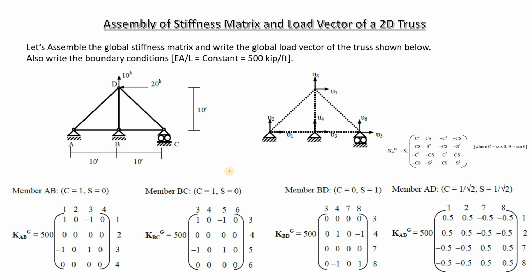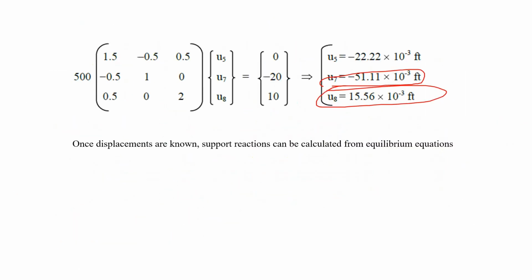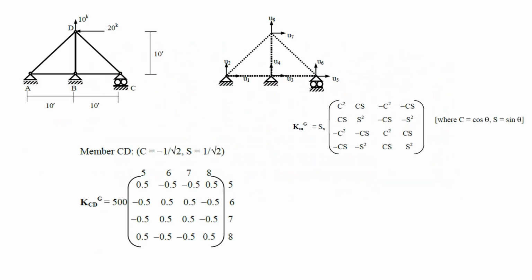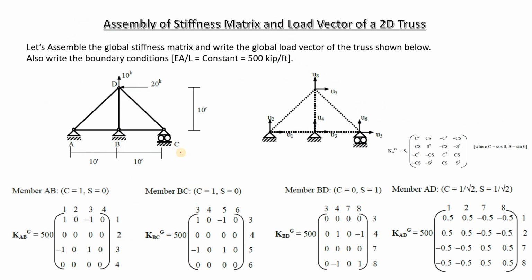The only hassle here is that there are lots of calculations if we use the direct stiffness method, right? But there are a smaller number of calculations if we use the joint method or the section method. But the thing is that the direct stiffness method is more accurate, as we have discussed in the first lecture. And since this is very lengthy, the solution is to use a programming language. A programming language is used to make this lengthy calculation shorter, and since this lengthy calculation is more accurate, with the help of a programming language we can get more accurate analysis in lesser time.